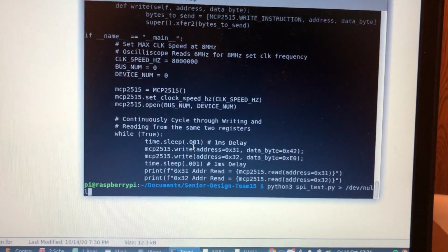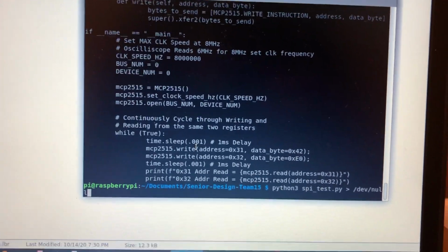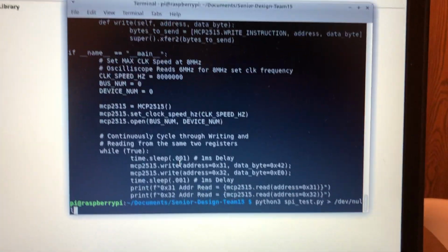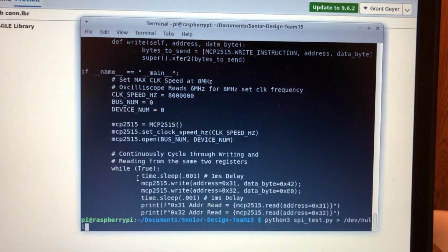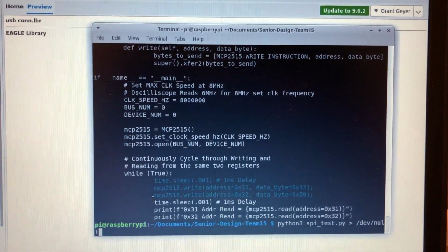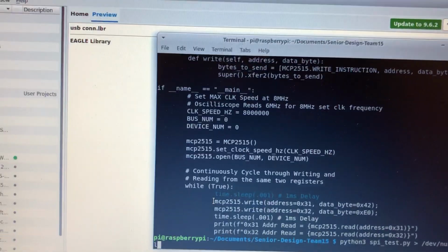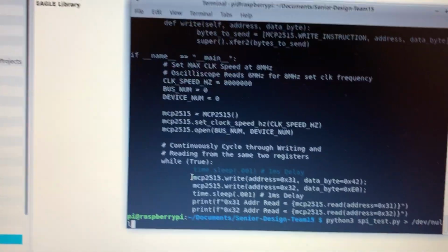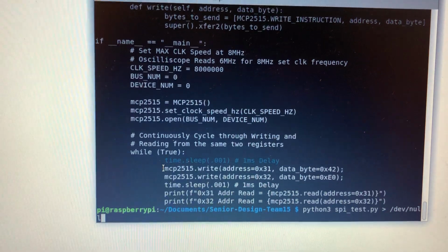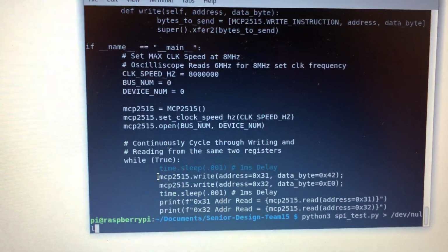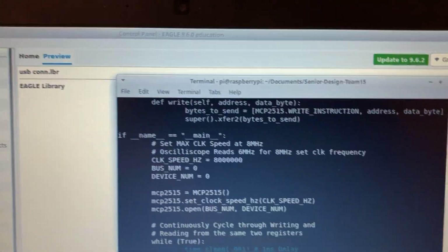First up, we're demonstrating the functionality of reading SPI packets. We have a script that sends different data over the SPI bus. It'll first do 2 writes, which start with 00, with the address and data following, then 2 reads, which start with 03, then again address and data following. So we will start running that.